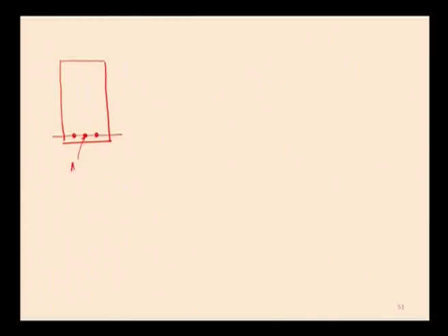This is the total AST required for the section, and this is the area of compression reinforcement, which is denoted by ASC, which is placed at d dash from the topmost extreme fiber, and b is the breadth of beam and small d is the effective depth of beam. This is a doubly reinforced rectangular section.